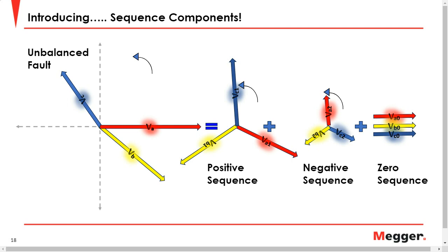Our next question here is for Jacob. They ask, I've tested negative sequence pickups before, and they seem to pick up well before expected. Why is that? So first thing, you can hear me, correct, Griffin? Yep, we can hear you. Perfect. All right, so you have to look at relay to relay how the element is actually measuring and responding to negative sequence, because it's not always going to be set in just pure I2.